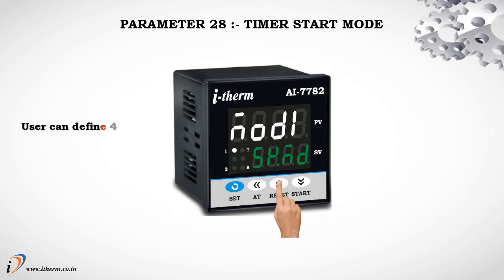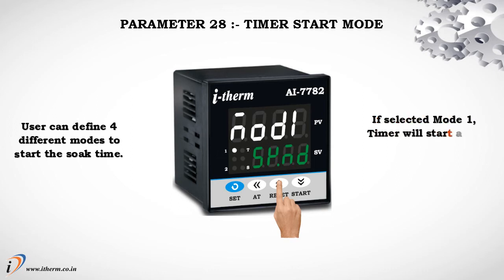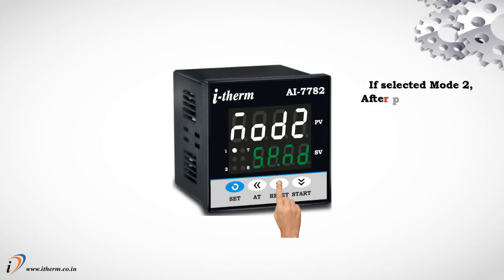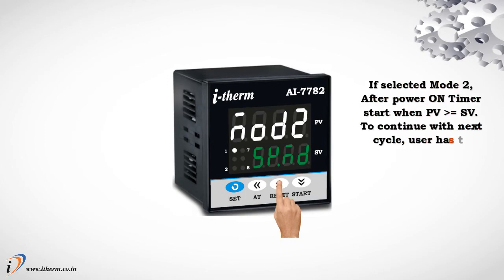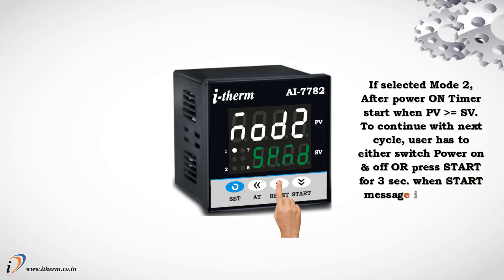Parameter 28, timer start mode. User can define 4 different modes to start the soak time. If selected mode 1, timer will start after pressing start key for 3 seconds, irrespective of process value. If selected mode 2, after power on, timer starts when process value is greater than or equal to set point value. To continue with next cycle, user has to either switch power on and off or press start for 3 seconds, when start message is displayed on the lower display.